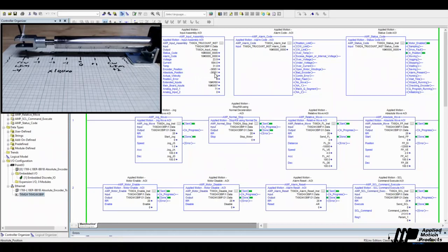So we're going to pull the power, and we're going to be able to tell that the power is pulled because that AOI block is going to stop refreshing. The input assembly is going to stop refreshing, and we're going to see an error down here on the TXM24 EtherNet device. You see that little yellow triangle with an exclamation mark in it. So now we've stopped refreshing. You can see this data is stale.